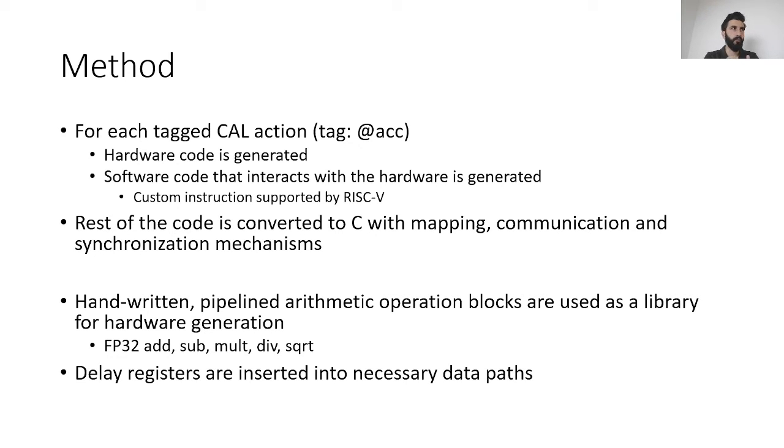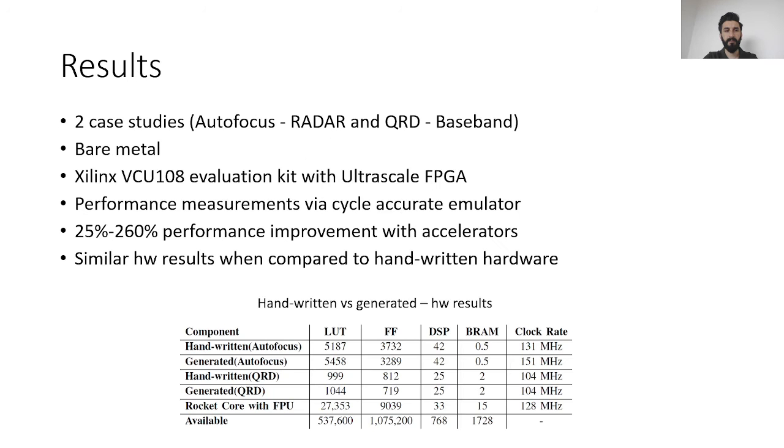And during the hardware generation, we use handwritten and pipelined arithmetic operation blocks as a library. And we also use delay registers to actually support the pipelining. And we put these delay registers in the necessary paths, into necessary data paths.